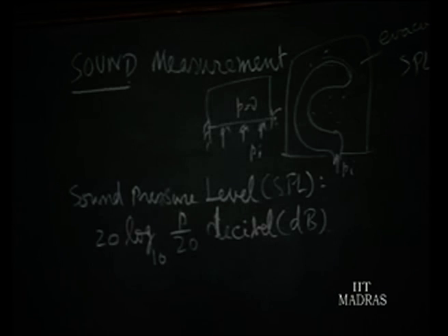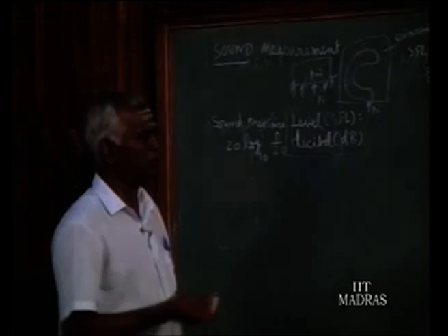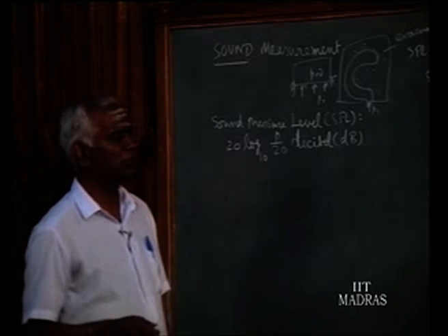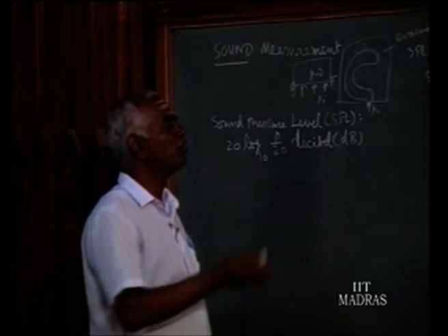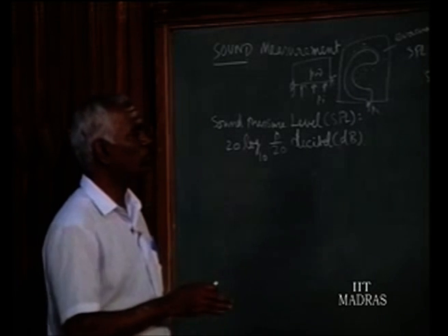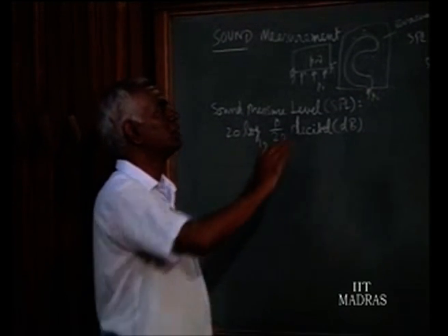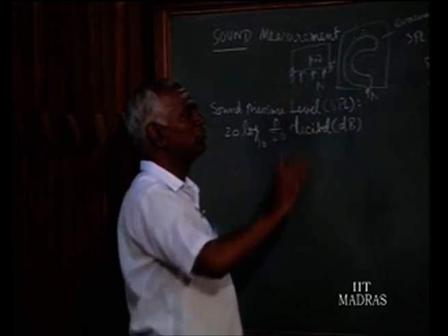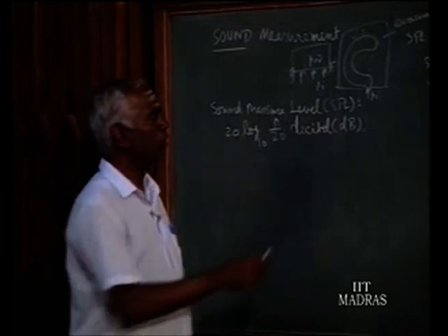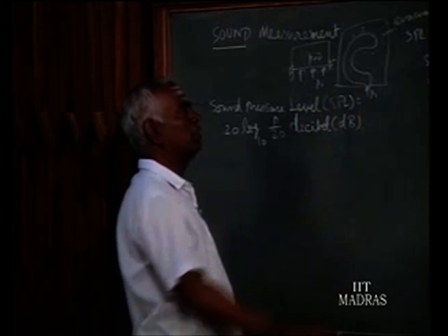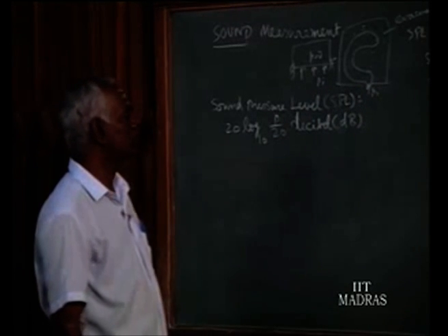low and moderate values. Other methods we have seen in detail last class, that is McLeod gauge, viscous vacuum gauge, Pirani gauge and all other methods. Otherwise, whatever method we use for pressure measurement we can use, provided the surrounding in which the instrument is placed is evacuated and the absolute vacuum pressure is applied inside the tube. That way we can measure it.